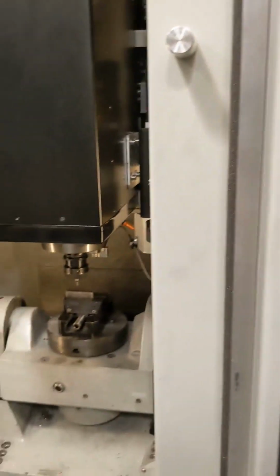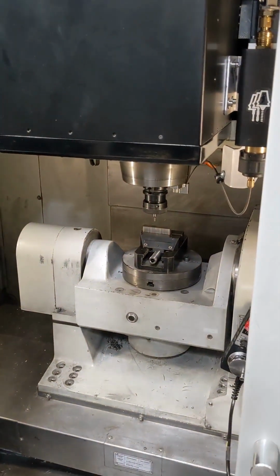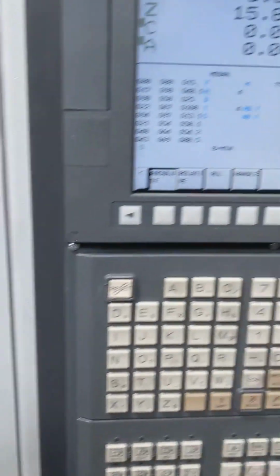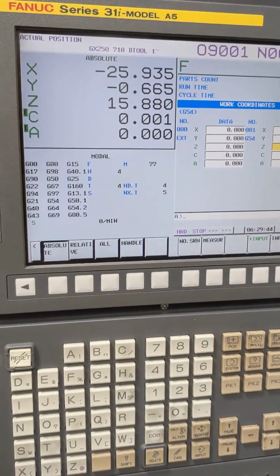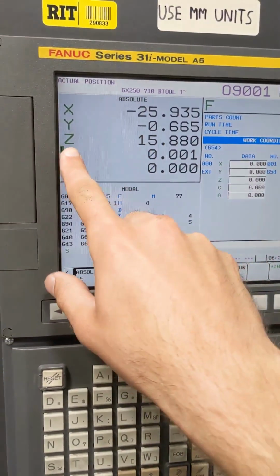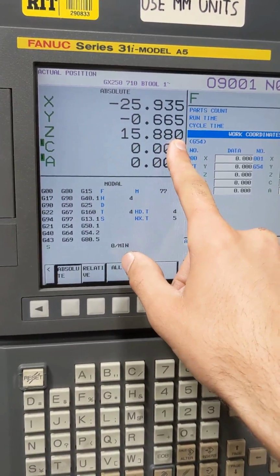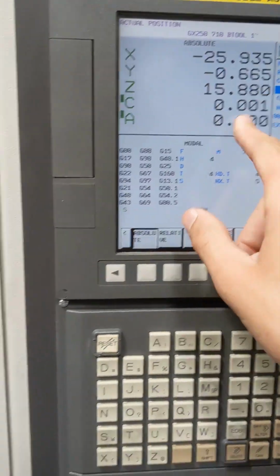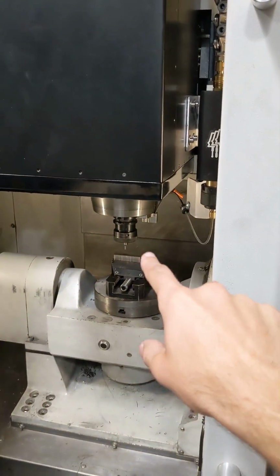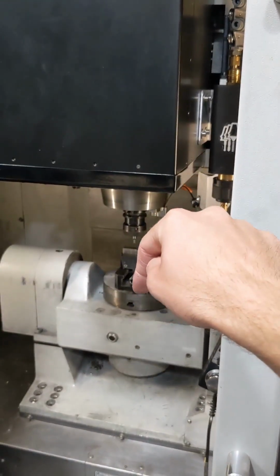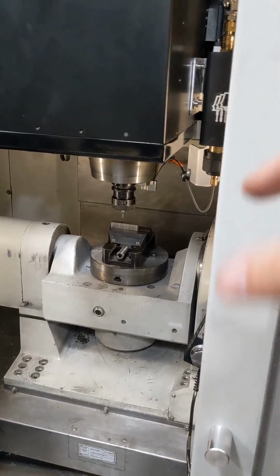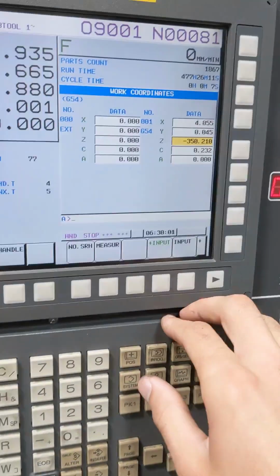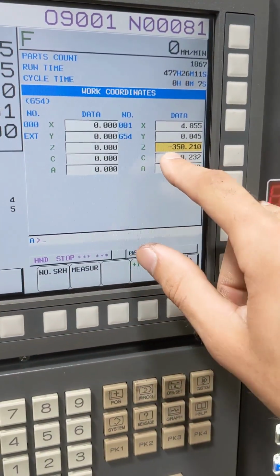That means that the current location where we just had the pin just slide under the tool is now assigned as our 15.88 location. Remember that you have to have the tool height measured in here, otherwise the machine won't compensate your tool height and it'll try running the spindle at the location where the bottom of the tool is right now, which would be bad. It's also a good check to note this number.